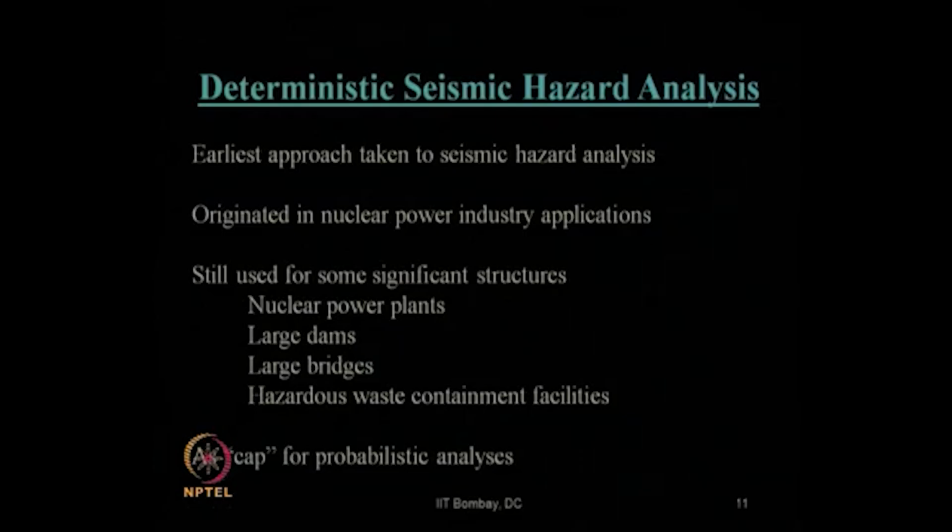Okay. For India, suppose we plan a proposed nuclear power plant at a particular site. If you want to go for seismic hazard analysis, you have to go for deterministic seismic hazard analysis only. Probabilistic will be more logical technically, yes, but that can be considered as a subsection, just a way of looking from the technical point of view at how much it varies from your design value, which is proposed through the deterministic seismic hazard analysis.